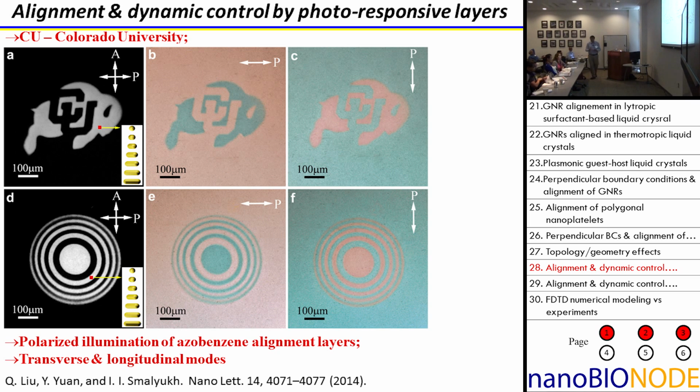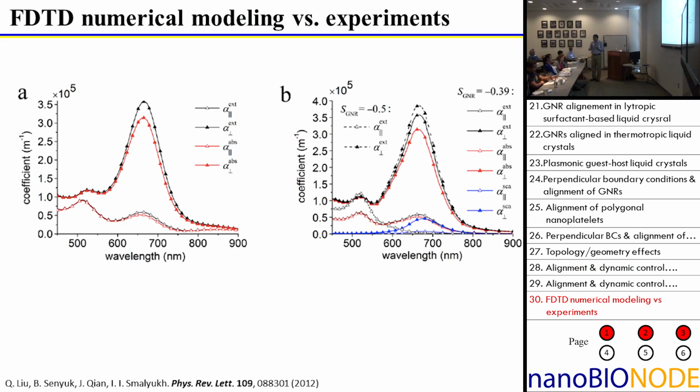And so now as we design all of those types of response of dispersions of nanoparticles in liquid crystal media, we can then computer simulate using approaches like the discrete dipole approximation that we discussed, or FDTD, and predict what kind of response we should have for this ordered dispersion of nanoparticles, compare it to experiment, and you can see how good the agreement is, right?